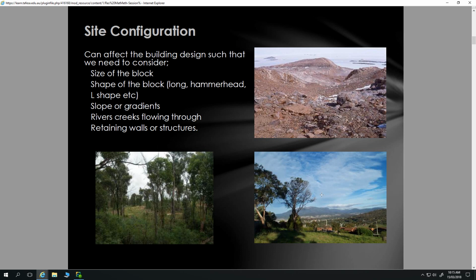So if we've got a block of land that slopes like this, for example, and we want to get a house onto that. Council says, well, we don't want that, so we do a driveway like that and then an elevated house out here, with a funky roof on it. Council don't really want that type of thing because that stands out extremely well against the Hills Face. So they prefer that you sink it in. So we go through the process of cutting and filling the land, but council says also we don't want you building on this fill section.